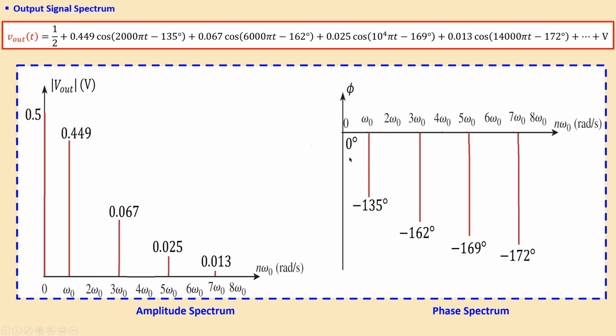What you see is the phase will approach approximately minus 180 degrees if you move on with your harmonics to 9th harmonics and 11th harmonics. And if you move on with your harmonics in the amplitude, it will approach approximately the value of 0. So at some point, the harmonics will not contribute that much. That's actually for this situation.